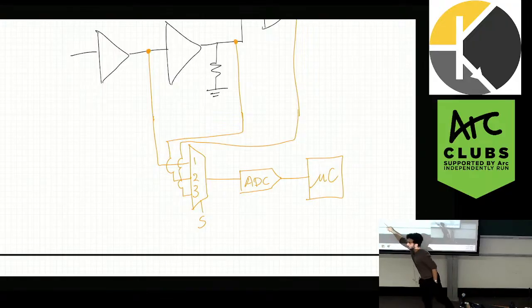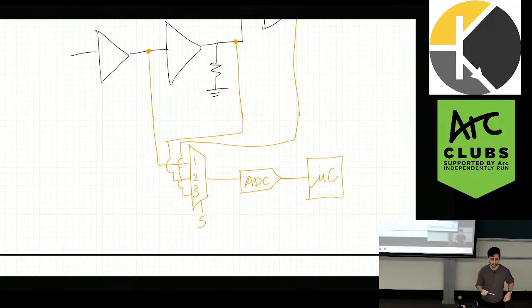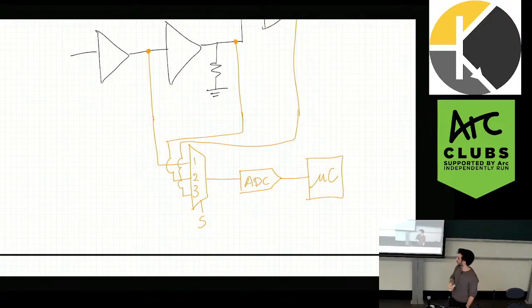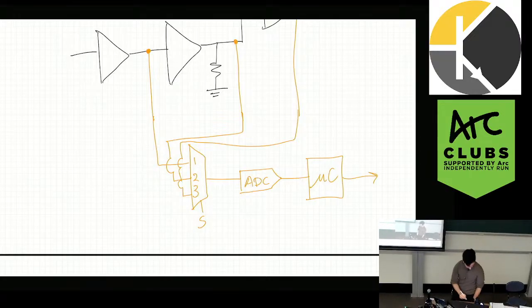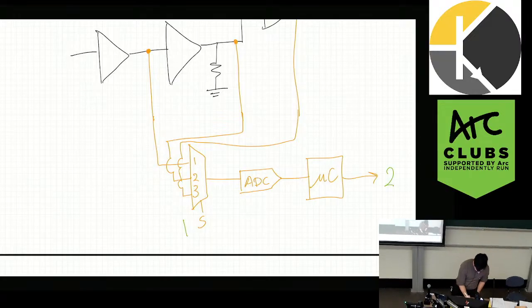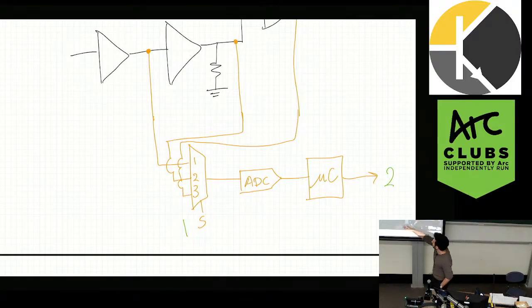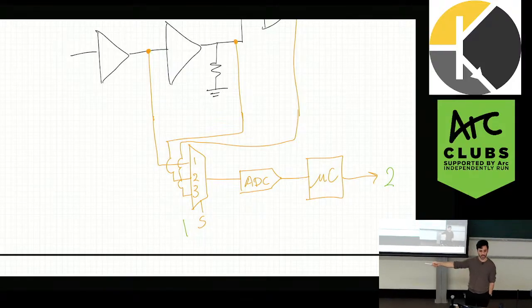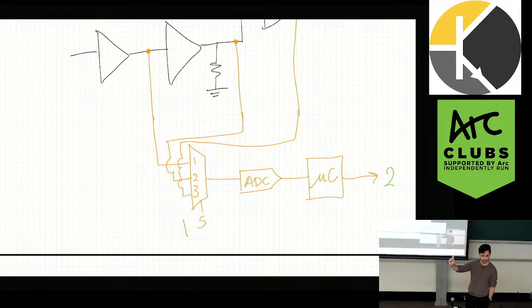So the S would essentially be a pin on your PCB, or your packaged PCB. So a pin there, and then you'd also have a pin here. So 2 pins, as opposed to needing 10 pins for all these different things I want to check. Does that make sense? This is generally how it's done. Because again, everything is easy when your design manager tells you, okay, you have 50 pins to use. In reality, you're only given like 3 or 4, right? So you have to get creative. And generally, on chips, we always do this sort of thing. Is that clear? Any questions?